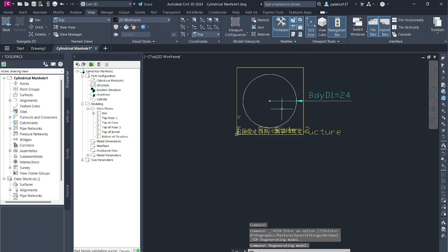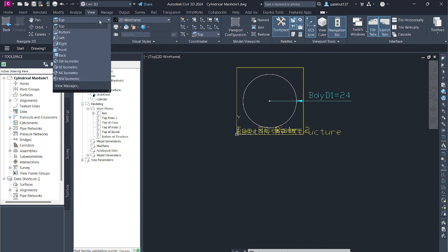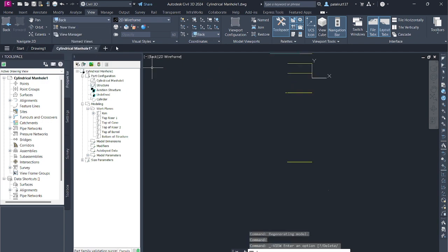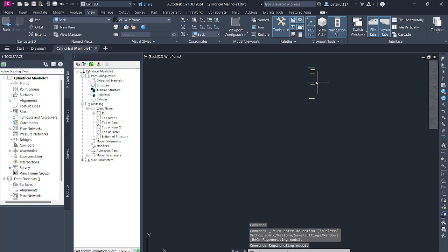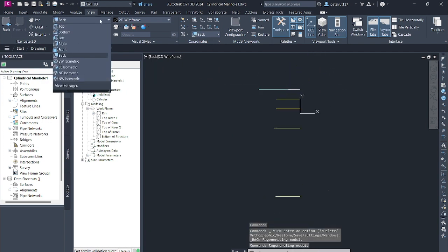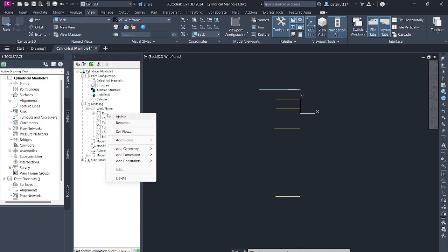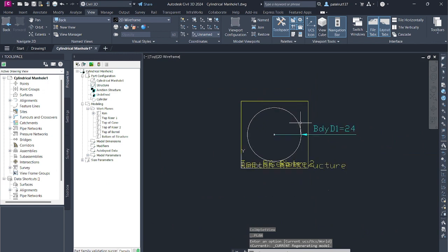Click Home tab, Create Design panel, Part Builder. Select Manhole 206 Type A, and then click Modify Part Sizes. Part Builder opens to your custom part. Add some variables to the cone height, SCH, riser 1 height, SRZ1, and barrel height, SBH, to make it easier to edit your structure after it has been inserted into the drawing.